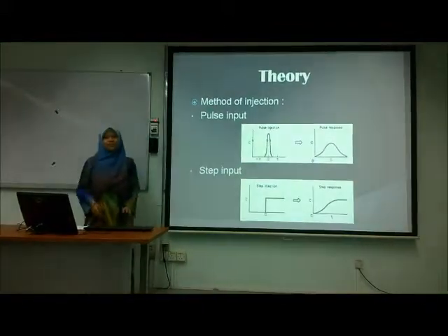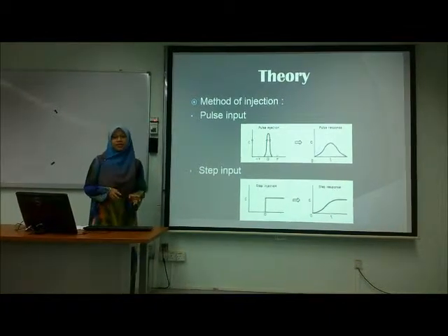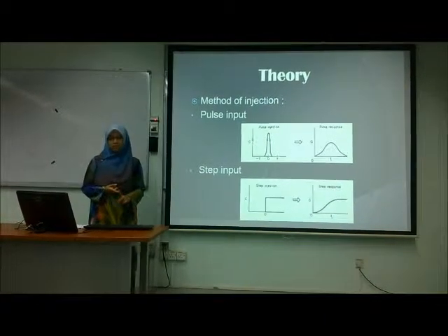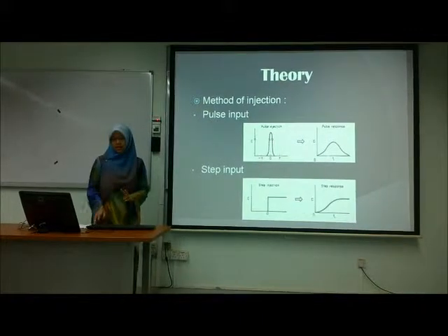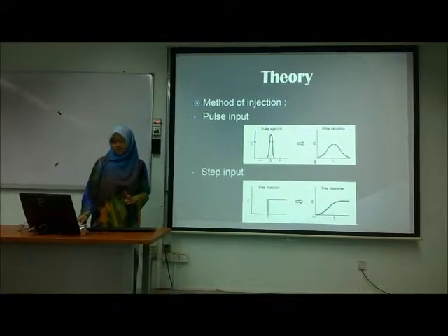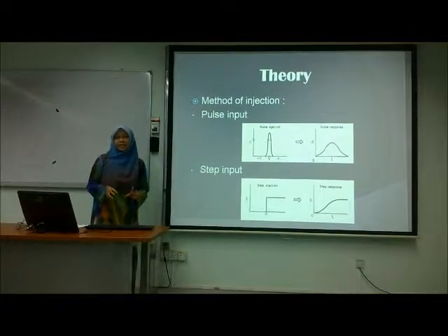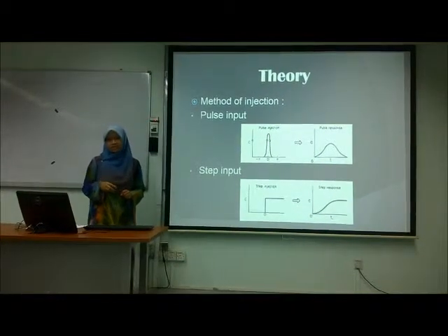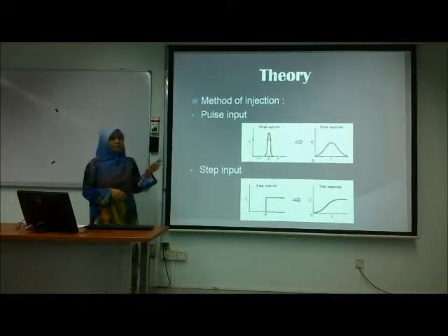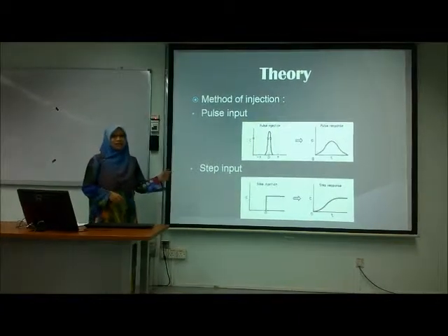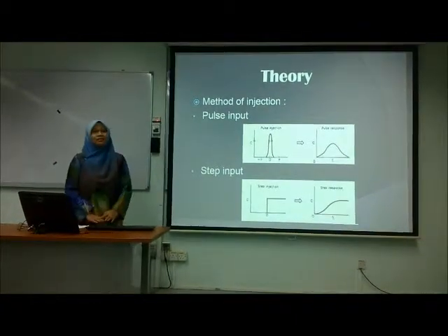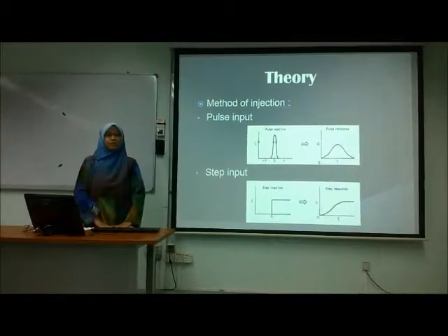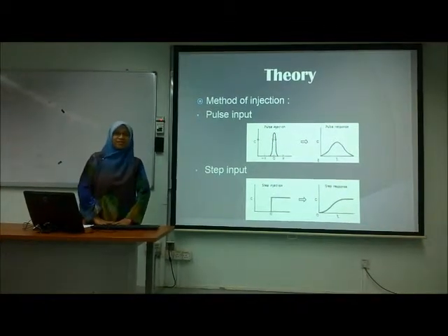There are two methods of injection of the tracer to the reactor. First is pulse input and second is step input. The function of residence time distribution can be extracted by the tracer response curve of concentration versus time as shown in the figure. Later, I will pass the floor to Ani, who will explain about the calculation and result from the experiment.